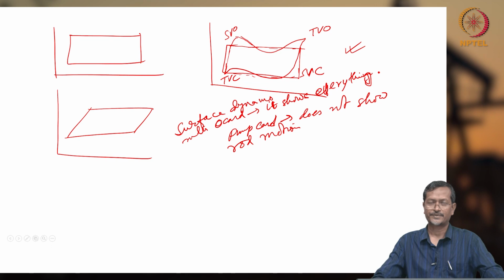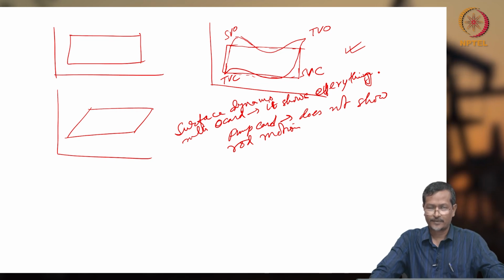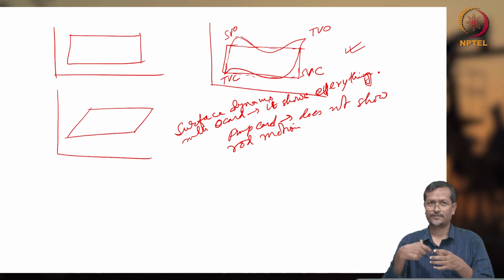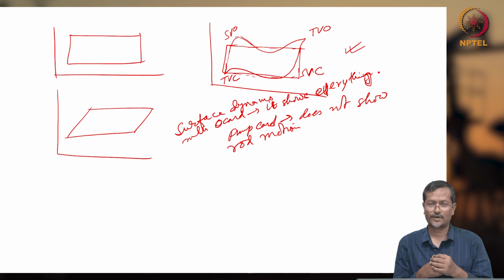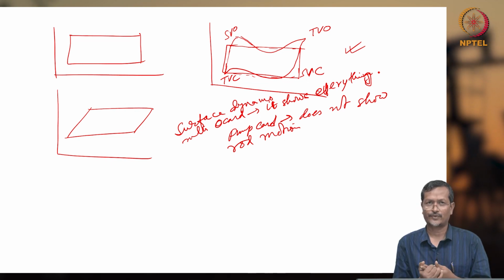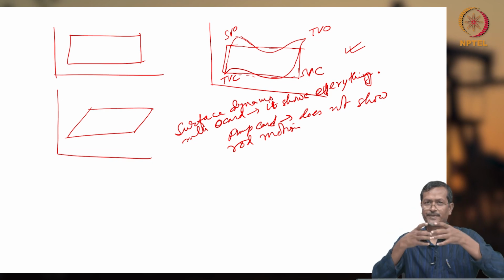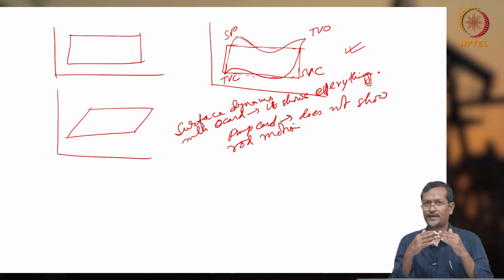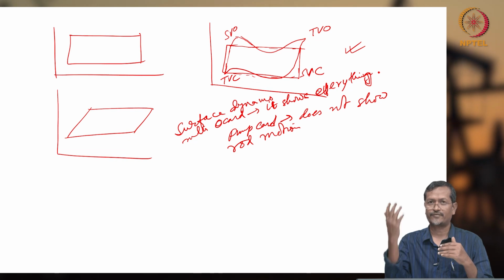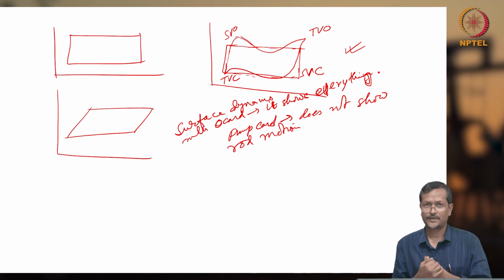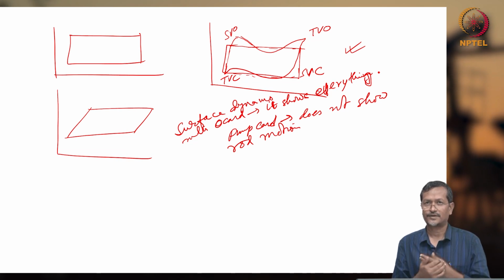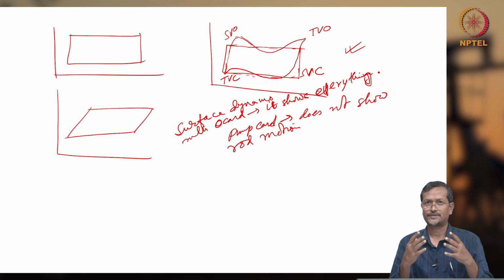Why is this dynamometer curve required? If you have the dynamometer curve, then you can understand whether your pump fillage is there or not, whether tubing is having any problem or not. So many parameters or properties of the wellbore and your pumping system you can understand from this dynamometer curve. And if you approximate through wave equations, I can eliminate this tubing and rod effect, then you can get an idealized curve. So to understand the whole pumping system, you have to understand the dynamometer curve and pump curve, so that you can understand your wellbore and your pumping system performance also.